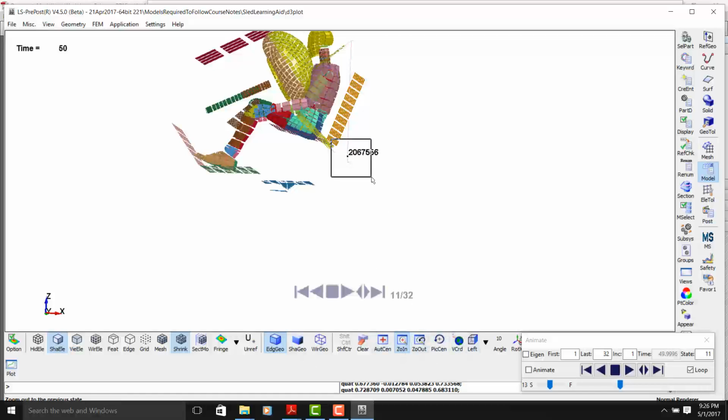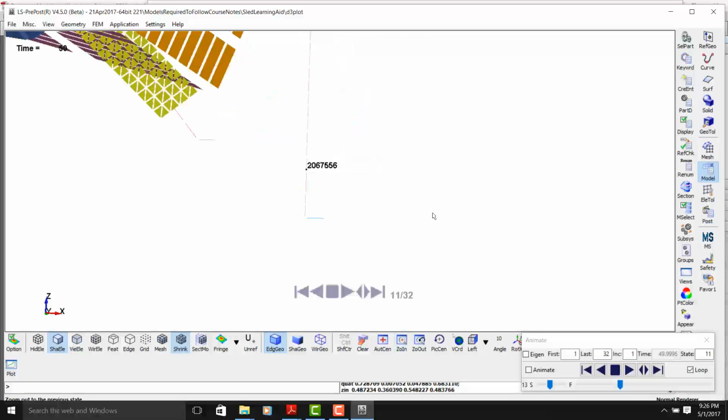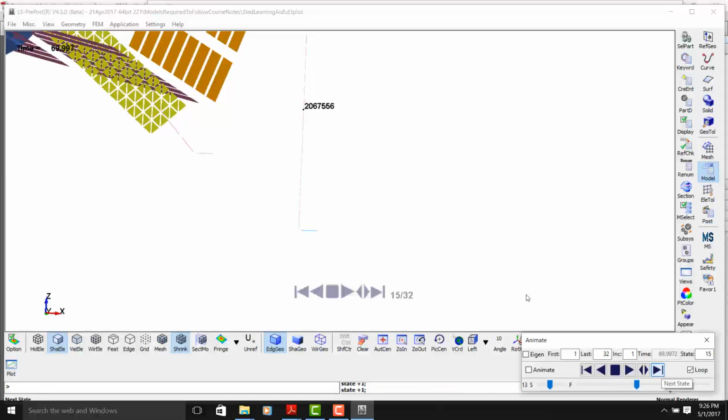Okay, the pyro pretensioner's action is somewhere after it fires, it finishes within the next 10 milliseconds. So by about 25 milliseconds, the pyro pretensioner action is over. Its purpose is to tighten the belt initially, and then when the dummy starts pulling it, the belt starts spooling out again. And you can see it's going up and up because of the dummy pull.